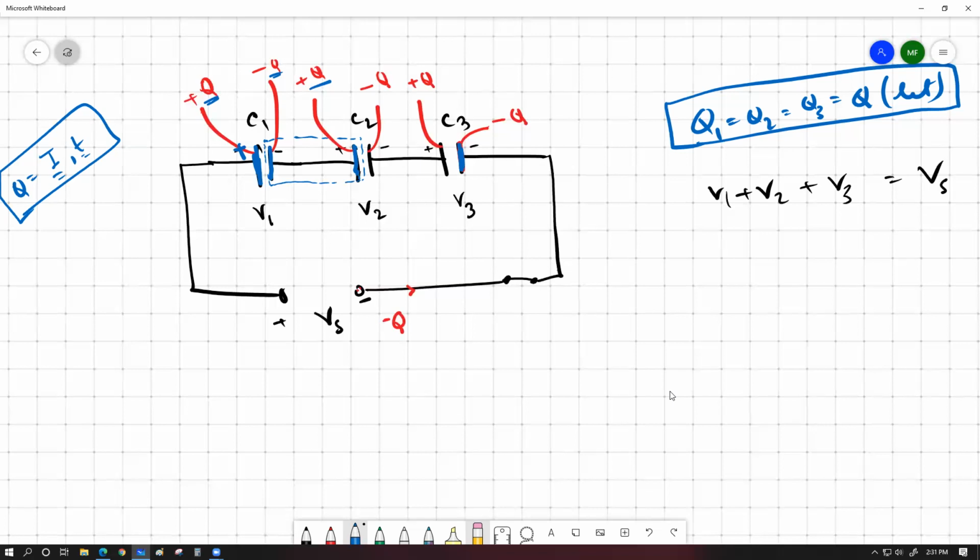They're going to be charged over time simultaneously. So it's not like this one charges up first, this one finishes charging, then this one charges up. No, not like that. What I mean is that if we attach multiple different voltmeters over here, let's say this is voltmeter 1, this is another voltmeter, and this is another voltmeter, and we connect them across these capacitors individually to see their voltage development, what we'll see is that the moment we close the switch, all of these 3 voltmeters are going to start to build up voltage values, but they're not going to be by equal amount.